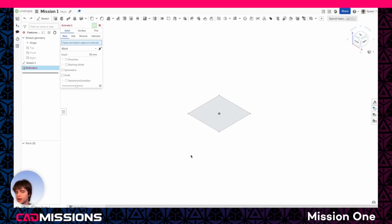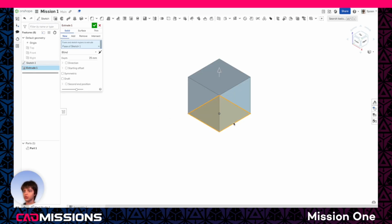Click that, and what extrude does, it takes a 2D drawing or something, and it'll just make it 3D. So we'll press extrude, and we'll click what we want to make 3D. So that. And you can kind of see how extrude works. That's why I made you go into isometric view. Because if you grab this arrow and you drag, you see kind of what it's doing. It's taking the 2D shape that we made, the square, and it's making it into a cube.